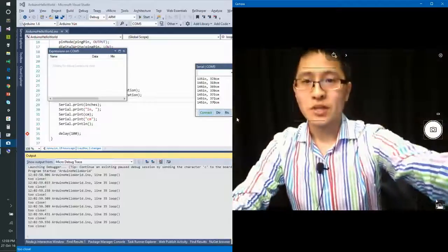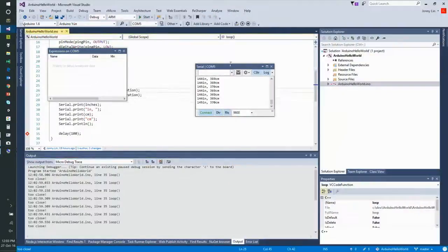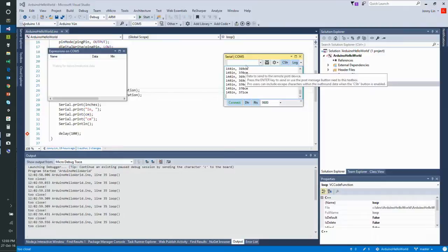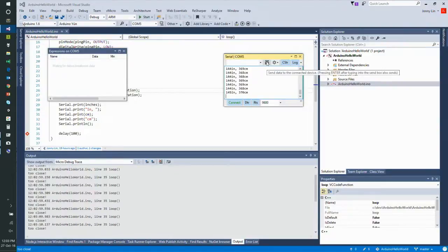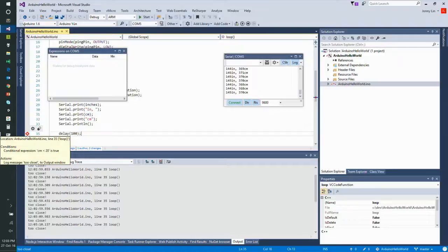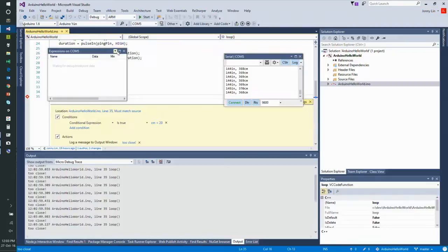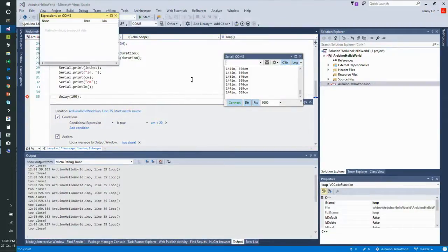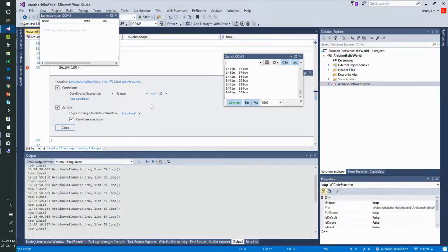Cool. Okay, that's pretty simple, right? You just plug in, and this serial port just pops out automatically. I didn't even need to configure any of the baud rates, which is pretty neat. But what you see over here is a little dot. That's a debug point. Again, for those of you working with high-level languages, this is probably nothing to you. But for us lowly embedded programmers, this is amazing. It took me like 3 days to figure out how to do printf without overflowing the stack. Let's put it that way.